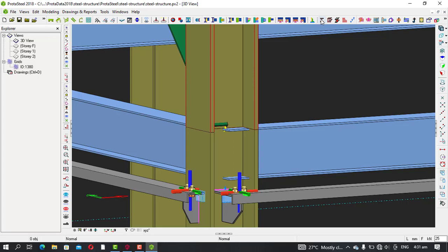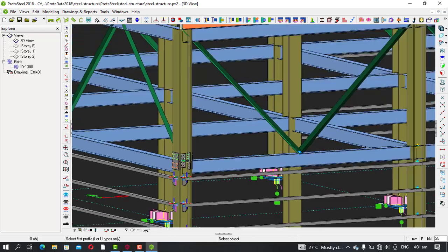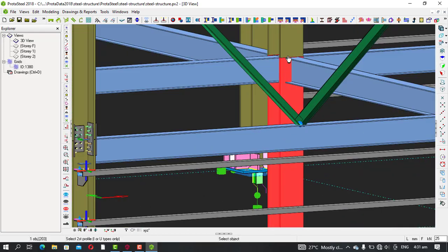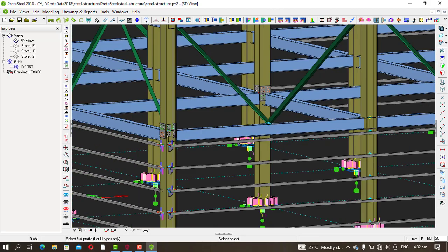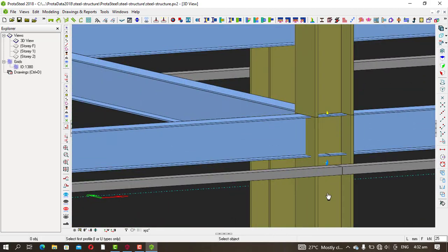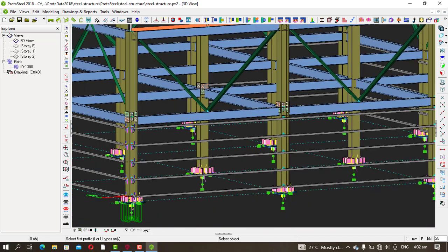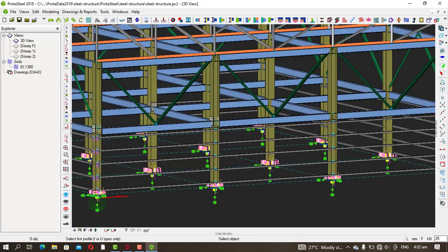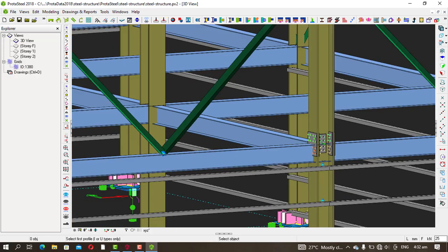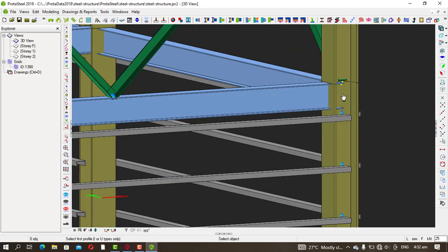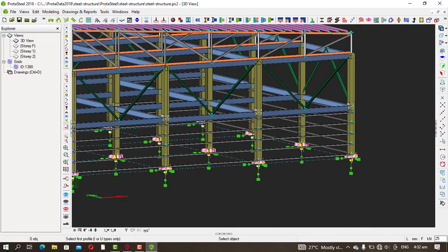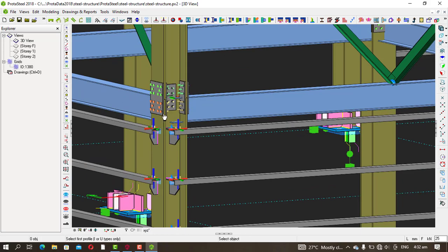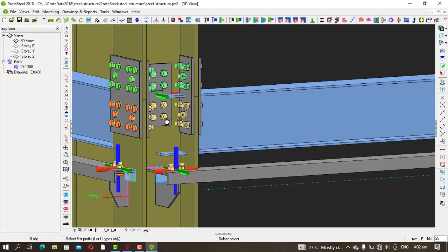You can come here, you pick the splice, pick the upper column, pick the lower column. That will do. You can even pick the lower column and then the higher column. It will still do. You can pick them as you like. Let me do here. So bottom up. Okay, you can say up bottom, doesn't matter. So that's how you go about doing that. Okay, so this and this, so you have that. Okay, so now you know how to connect the upper column to the lower column.